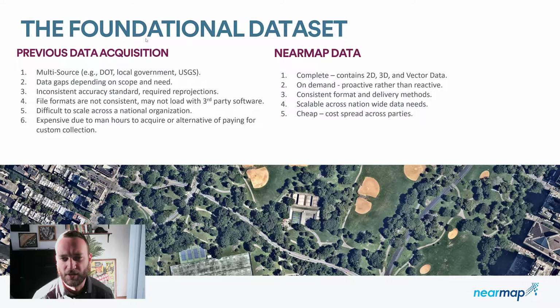So the current solution in a lot of cases is to multi-source this data acquisition. So to work with DOTs to leverage existing data collection, work with local government, work with maybe some free data sets like USGS, and piecemeal things together. So pull high-res imagery from one place, reproject it to the correct state plane that they need. And that needs to be done by a GIS professional usually.